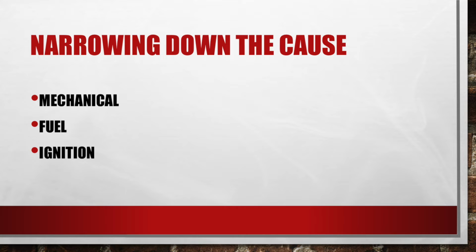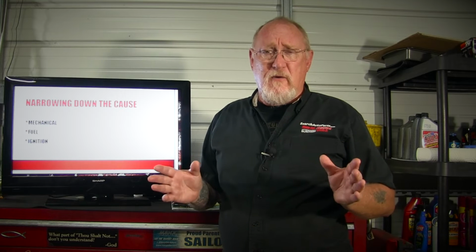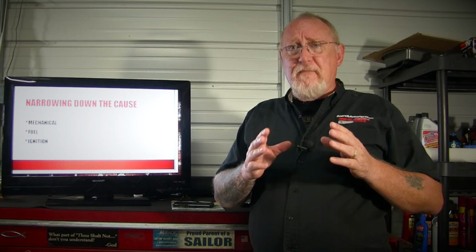Now, also consider, as I mentioned earlier, any factor that's going to cause less push in that cylinder can cause a misfire. So it's not limited to the ignition system. All too often, I see things online about techs that immediately go after the spark plugs, the coils. Maybe it's that term misfire. I don't know. But don't get that out of your system right off the bat.